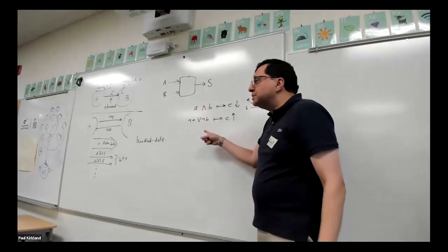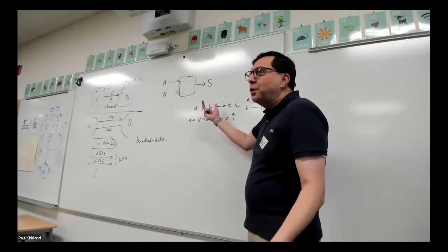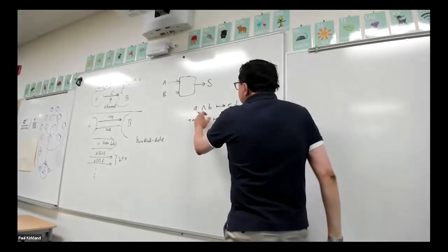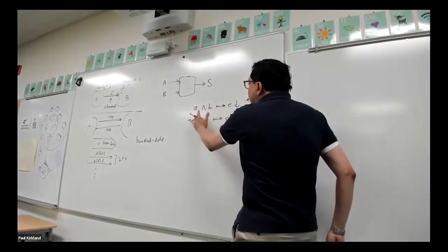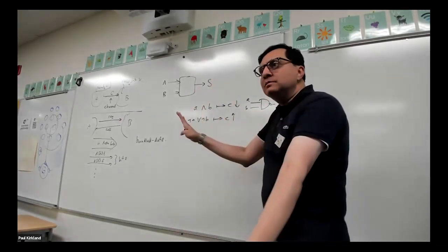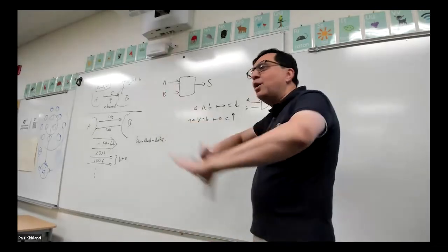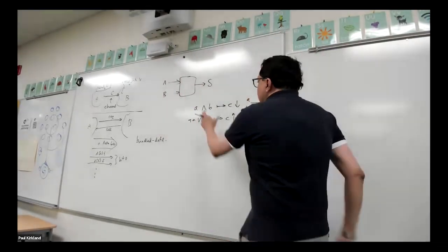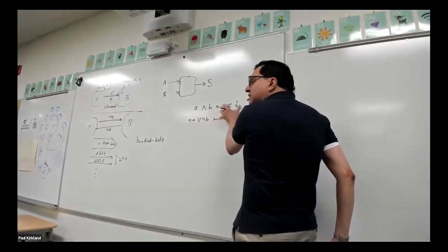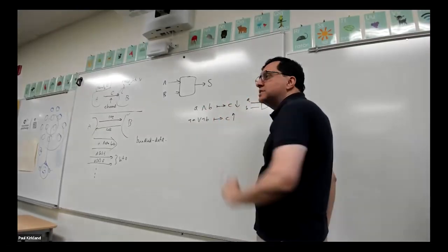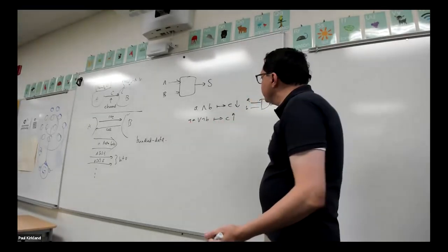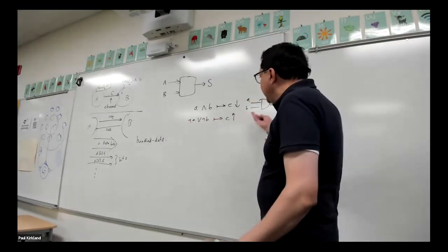These are called production rules. Again, this is old terminology from programming language theory from the 70s and 80s. The way to interpret these rules is they all run in parallel. Okay, there's no sequencing anymore. All semicolons are gone. There are no channels. Everything is 1 bit. This says if this is true, then you fire the right-hand side. And this says set C down, lower C. This says if this is true, raise C high. Okay. So this is a NAND gate.